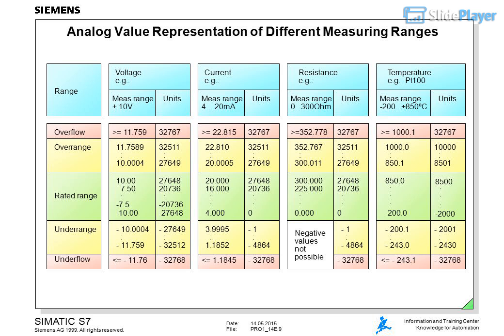Resistance: encoding the resistance ranges: 0 to 150 ohm, 0 to 300 ohm, 0 to 600 ohm. Temperatures are measured with resistance thermometers or thermocouples. Encoding results in a rated range of 10 times the temperature range.